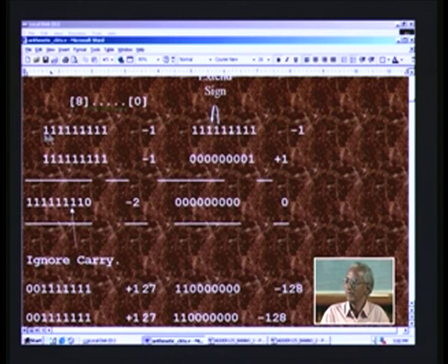So by looking at the MSB, you can distinguish whether this is in 2's complement. You can recognize this as a negative number, that is why you put a negative number here. And if you evaluate the 2's complement of this value, out comes the magnitude. Let us look at the 2's complement.